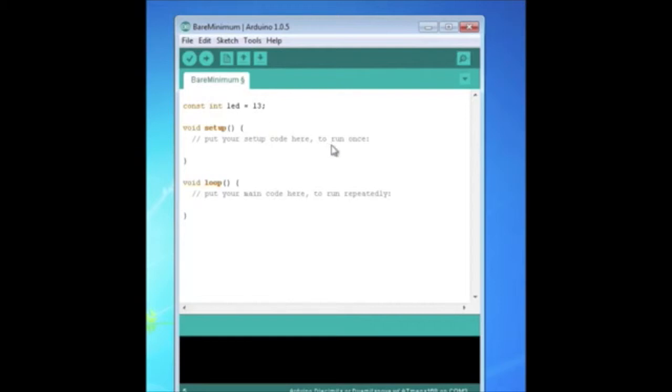All right, now I want to make the LED, pin number 13, an output. I can just use the function pinMode with LED and make sure that it is an output, so I assign the OUTPUT value to pinMode. In this lab, there is no extra configuration to be done, so I am finished with the setup function. Now the loop function.